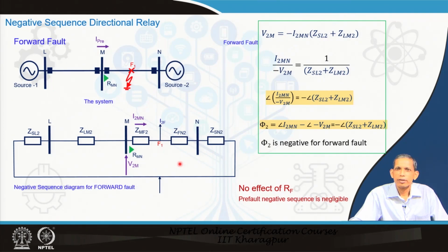Unlike load voltage, load current consists of the positive sequence component. So, positive sequence current in a transmission system is significantly high during normal conditions also. That affects the positive sequence fault current, as we have already observed through examples.